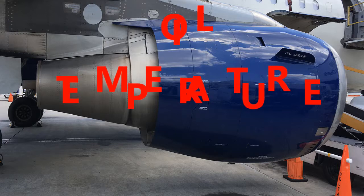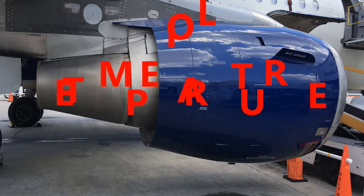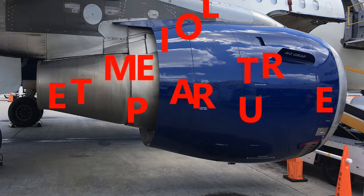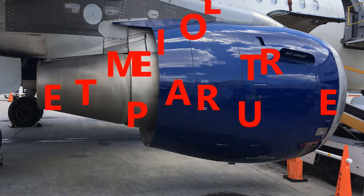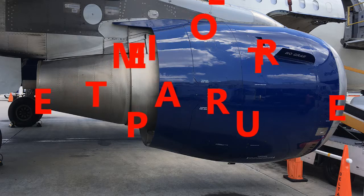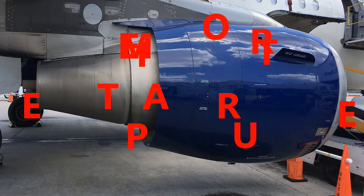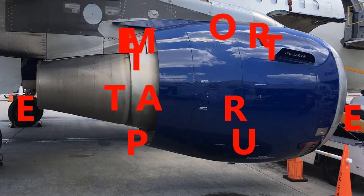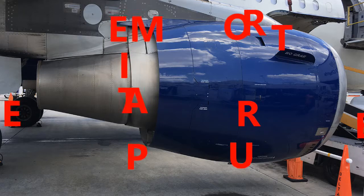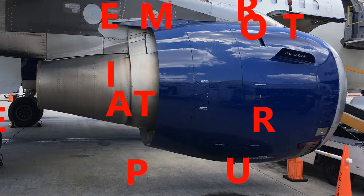Okay, all right. So we have the monitoring, like I mentioned before. On the temperature sensor, this one is located on the oil pressure filter. This is for the engine condition. I know just a bit ago I mentioned IDG cooling control, but here on the oil temperature sensor for the engine condition monitoring, this one is located on the oil pressure filter that's downstream of the pressure pump. Oil temperature is sensed by this sensor, and its range is a little bit